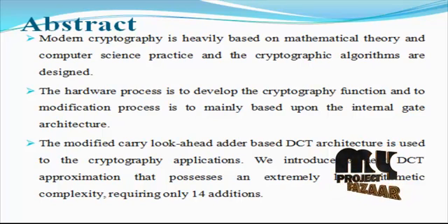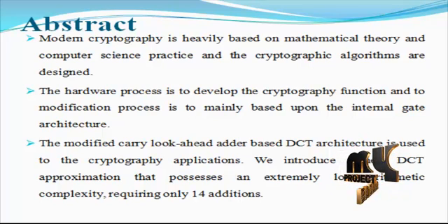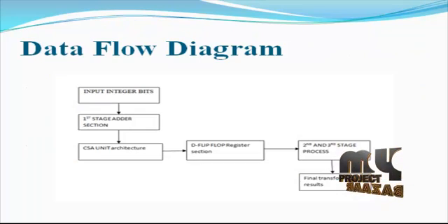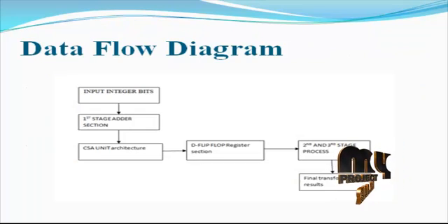Our proposed DCT architecture is designed in the VHDL language. Then we develop it in the Xilinx 14.2 software for the required 14-addition based DCT architecture. Next, we see the flow diagram for the project.